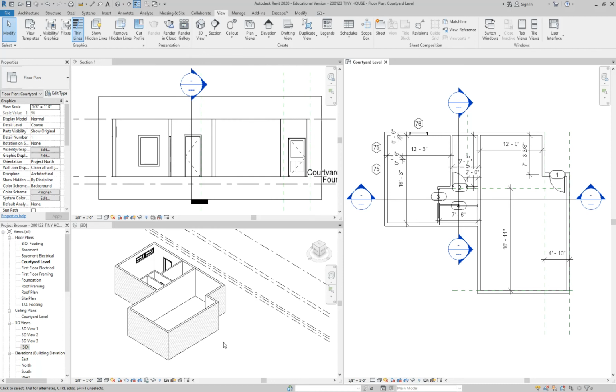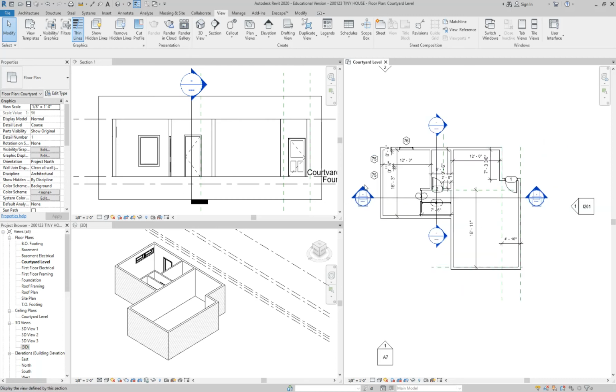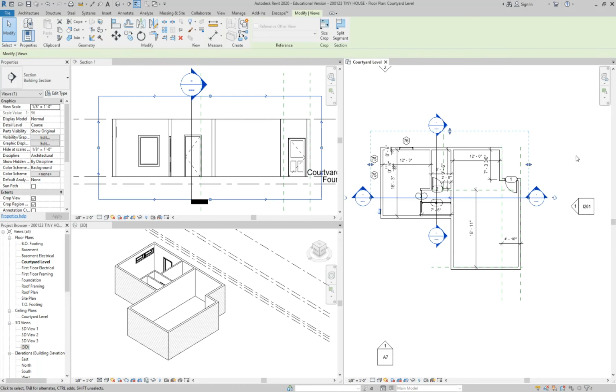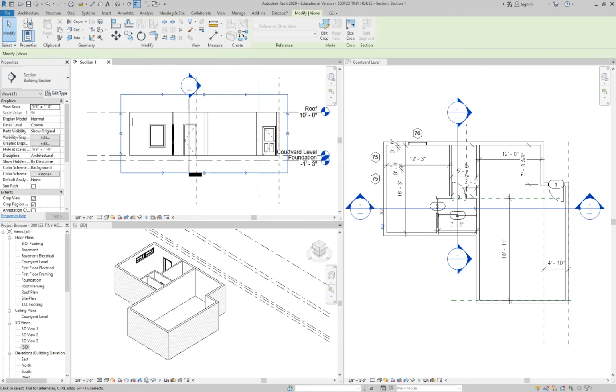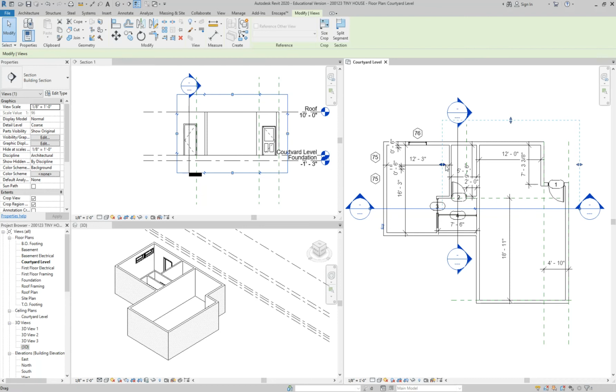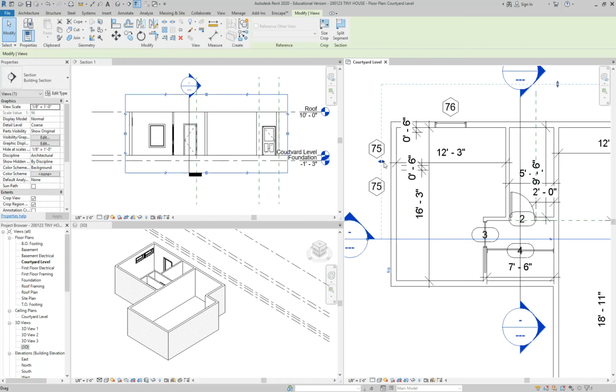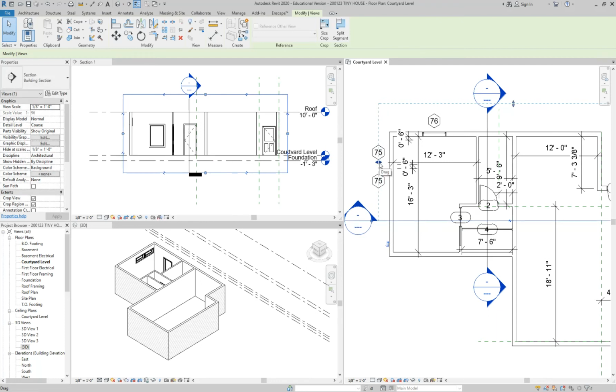So, troubleshooting, just in case this happens to you, if you have your arrow selected, there we go. Do you see this kind of bounding box that comes up? It's similar to our extents window. So if you're trying to drag your heads and you accidentally drag these boxes instead, tell me what happened to my view or my section. Yeah, so I'm clipping my section. So in case this happens on accident, just know that you can use these two triangles to change your extents on it. Okay?